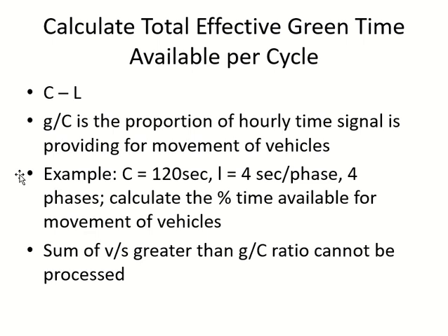Green time minus lost time? Green plus yellow plus all red. Yeah, phase time minus lost time. Okay, so this will give you total effective green for all the phases.